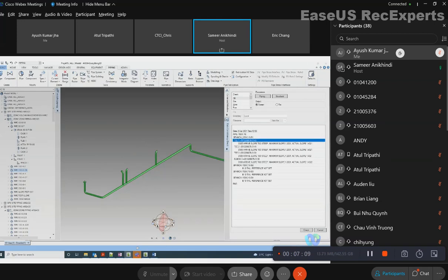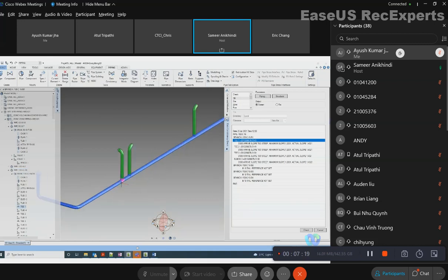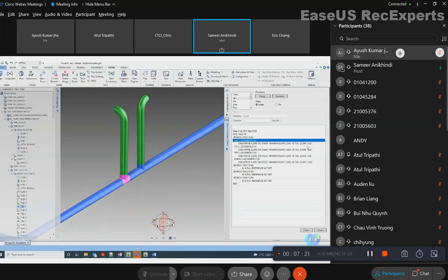So see, for components related to T1, 2, 3 and elbow, branch. So if I go here, T arrive slope is too steep, maximum slope is 1.2031 and it is 1.4. So here this maximum and minimum range is set in the catalog. Again, the catalog range has to be increased. What can be the maximum slope? Similarly for all these three Ts. For elbow, what is the problem? Arrive slope, all the slopes, these are the problems of the catalog's values.